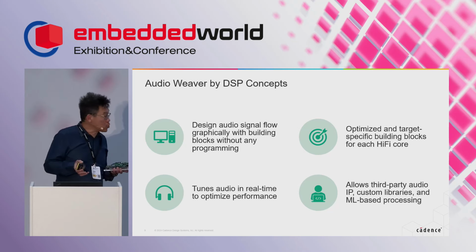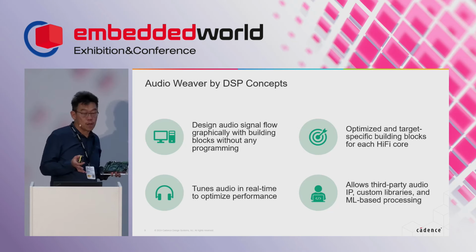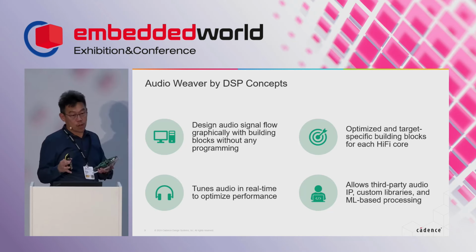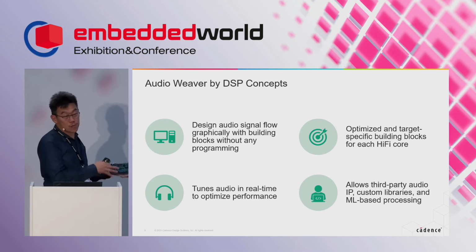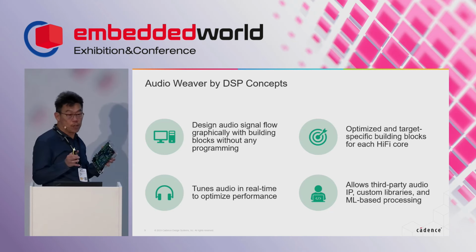So it allows you to tune the audio in real time on the PC, running Windows, and you hear the effect, and you can transfer the whole audio signal flow onto the HiFi 5 ADP. And later, when you have the module or product that is specifically running the same SoC, you can transfer the same audio flow into your actual product.